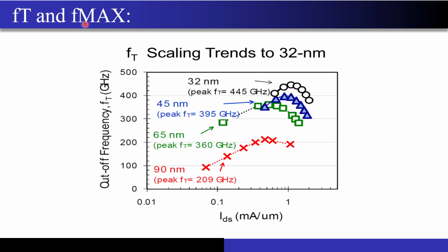And now there is also one thing called the Fmax. Now what is this Fmax? So Fmax is nothing but the frequency where the MOSFET's power gain will drop to a value of 1. So now if you operate beyond this particular frequency, the MOSFET will not give you any gain, it will actually start to attenuate, correct? So these are the two important figures of merit, and why do they matter so much?